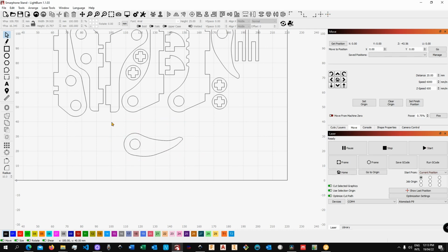These are, let's say, the major differences when using current position and when using instead a coordinate system which is relative to something known. So that could be the absolute one, using the machine coordinate system, or the custom coordinate system or user coordinate system. So that's something that you want to keep in mind.